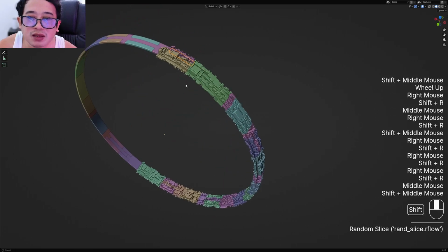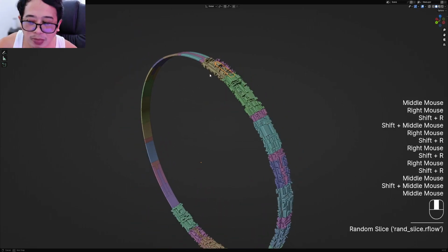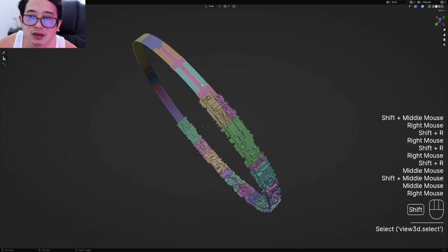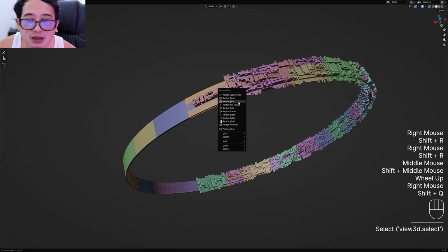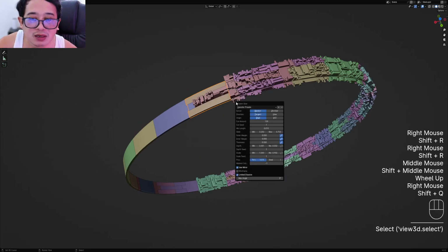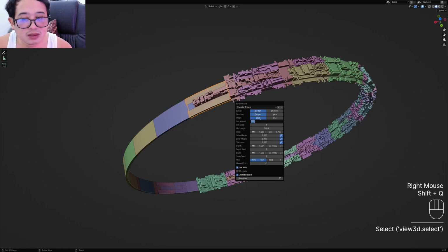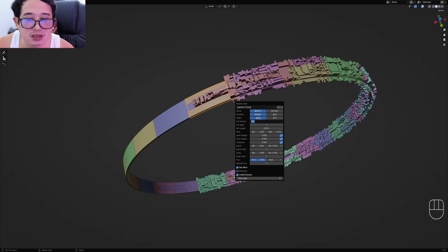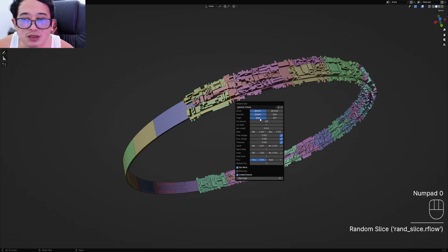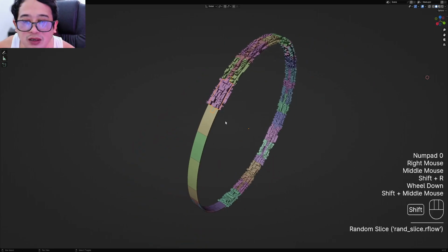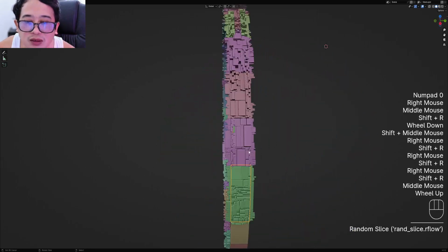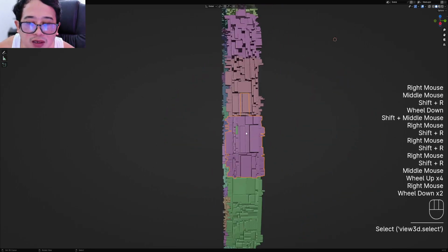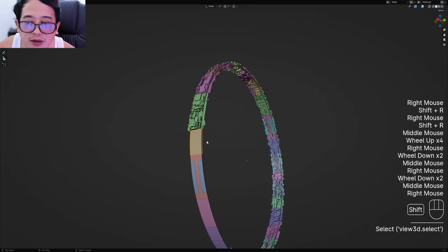If you did something that has erased the last action used by the repeat action command, which is Shift R, then you can just reuse the operator again, and just remember the cut amount you used, because this resets to 100 to avoid crashes for each operation. 400. Okay. Shift R, Shift R, Shift R. I think we have a really tiny, no, Shift R.